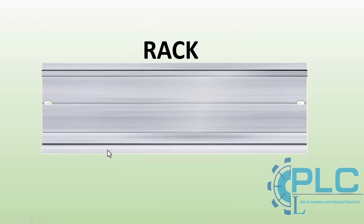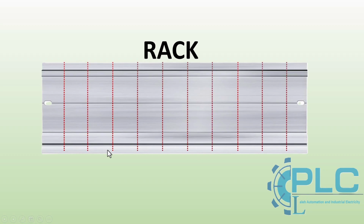In the S7-300 PLC, the rack is used to house the modules. It is made of aluminum and serves only as mechanical support for the modules. It does not provide electrical connections between them. For electrical connections, the system uses a bus connector, which enables communication between the modules. The rack comes in different sizes, and its selection depends on the number of modules required for the project. A larger rack can be cut to the required size if necessary.